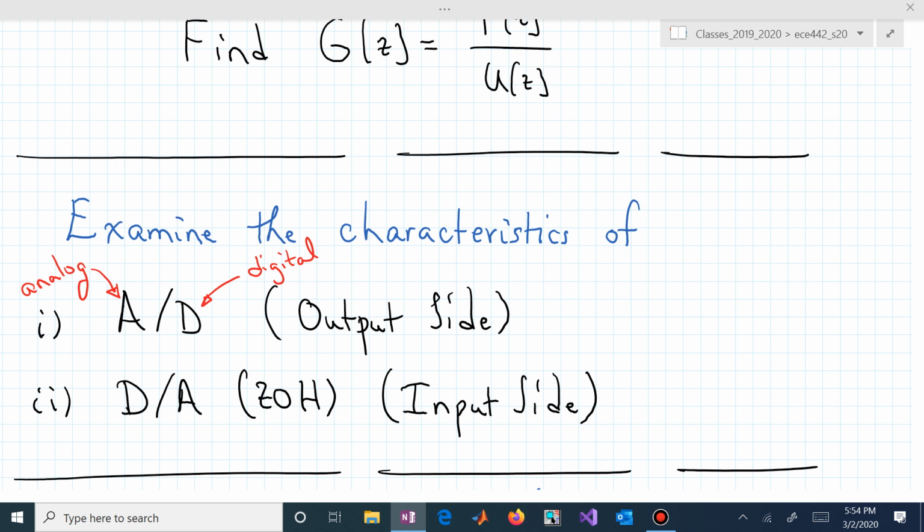I now hand you the next sample, which is 1.8. You just say, okay, 1.8 from now until the next sample. That's our zero order hold. I'm not trying to do any slopes. That might be a first order hold, if I said, oh, I'm trying to anticipate, I need a slope. No, we're just doing a constant, a zero order hold between the digital and the analog.